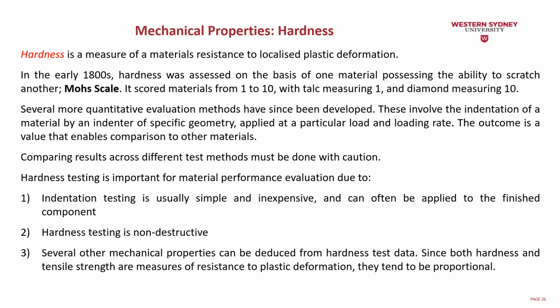Hardness testing is important for material performance evaluation because, first, indentation testing is usually simple and inexpensive, and can often be applied to the finished components. Hardness testing is also non-destructive. That means we don't have to break the material to make the test, just apply the force using the tool on a certain position and see how hard the material is.